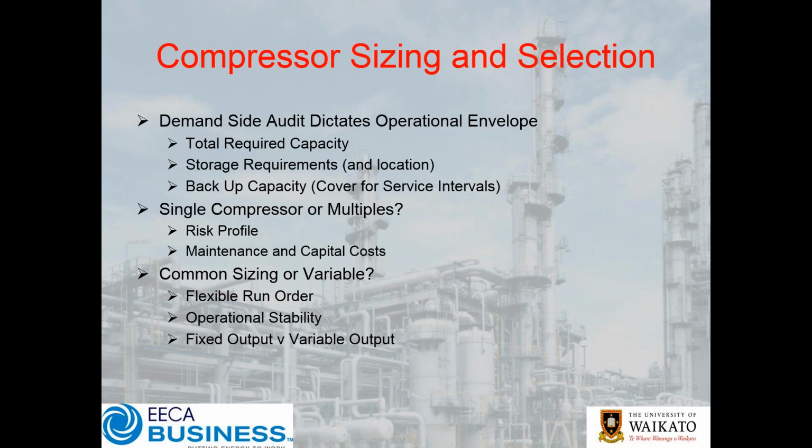Then when it comes to the sizing, there are a lot of people who do what I refer to as the poor man's VSD. This is where you might have multiple identically sized compressors, as opposed to getting the right mix of compressors to better match your demand envelope. And so getting fixed output versus variable output then becomes an important consideration.